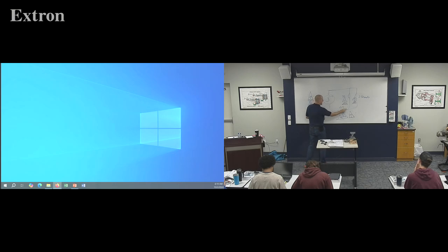So if we have 50 volts dropped across our resistor here, these ones are in parallel. If I'm coming from this point, I have 100 volts, I move my voltmeter to here, and I would still have 50 volts of pressure left, which means I have 50 volts across both of those, right? All right, here we go, next one.